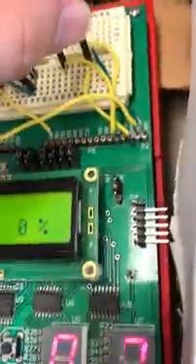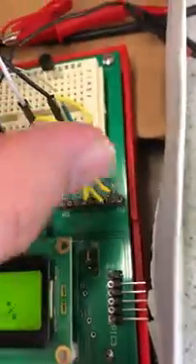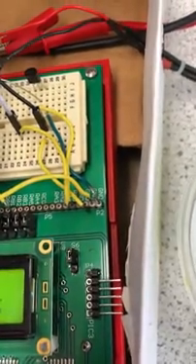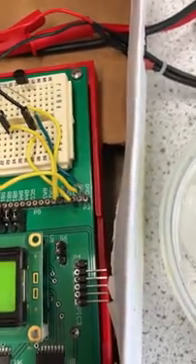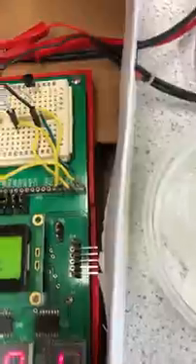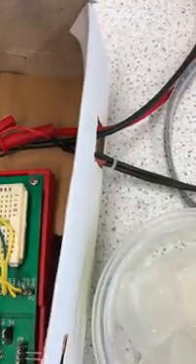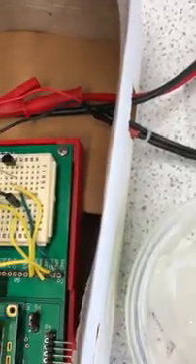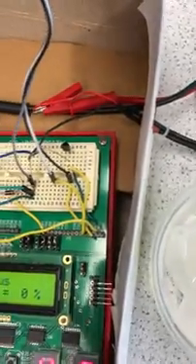Let me show you. The second pin, which is plus, is going into the 5 volt, which is also connected to the sensor port, and the third pin, which is S, is given to the RA1, which is the assigned port for the soil moisture sensor.